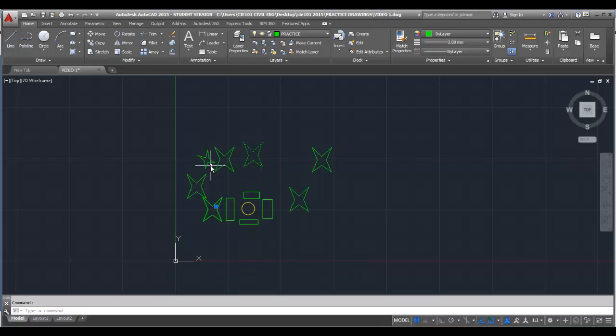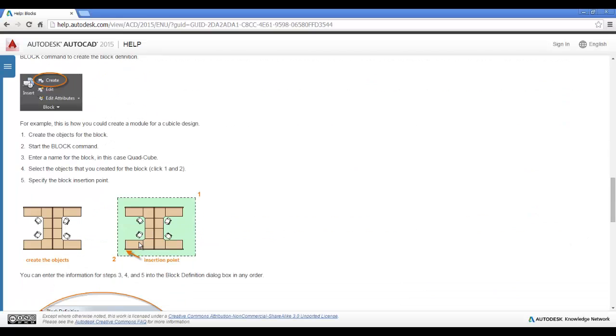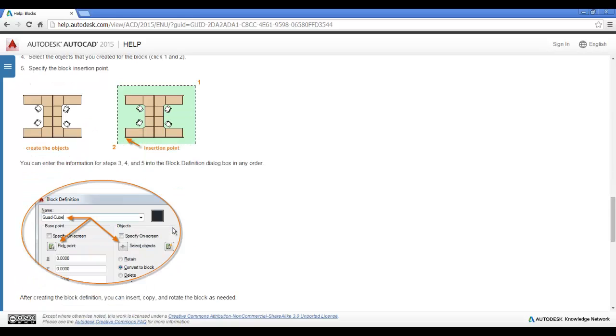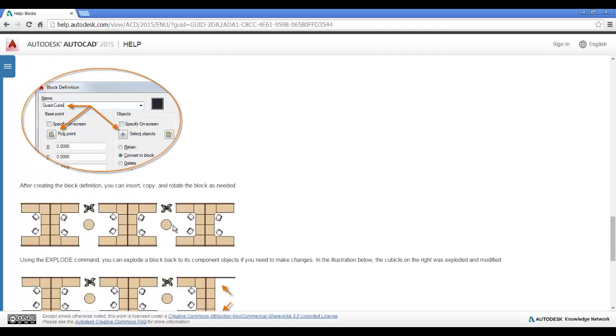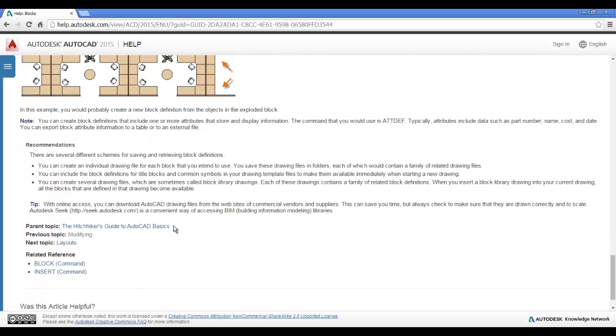You can see once they're blocks, they become rotatable. So I want to rotate this now. I can find this as my point, and you can rotate it, spin it around, different angles. I apologize for being a little sloppy on this, but this is a new version of AutoCAD, so some of my tool functions are a little bit different. So you can create blocks out of a series of furniture components. Anything can be a block, so we can place these in.